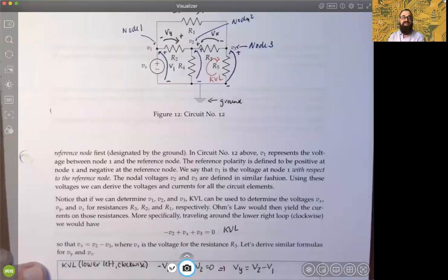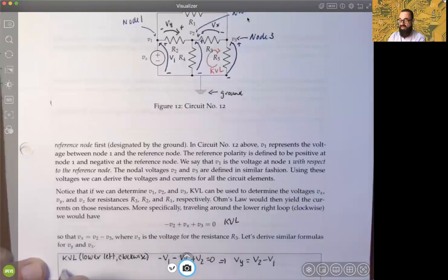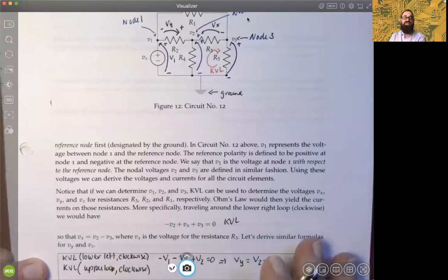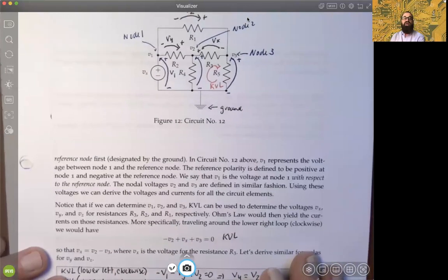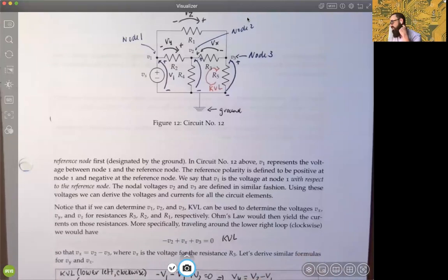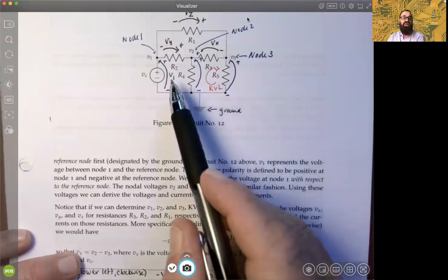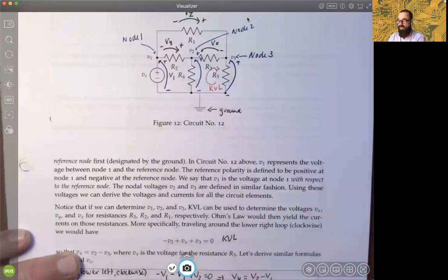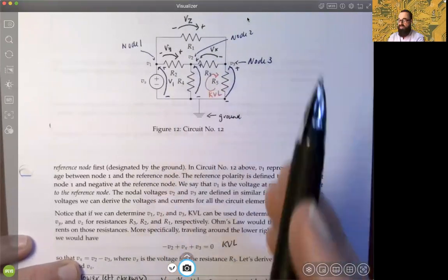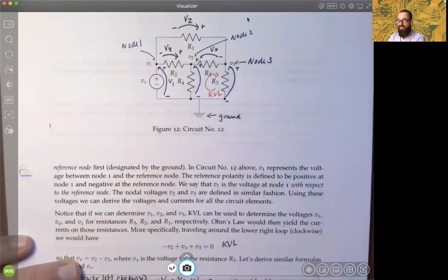And then finally, if we push up just a little bit here and do a KVL loop for the upper loop, and let's say we went clockwise again, what node voltages would we encounter? Again, we're trying to get a representation for Vz. So from the upper loop going clockwise, we would come into the positive pole for Vy, right? Then we'd be coming into the negative polarity for Vz, so we get minus Vz, okay?